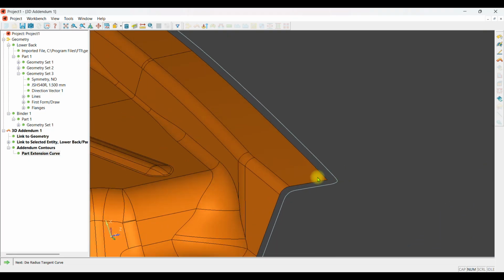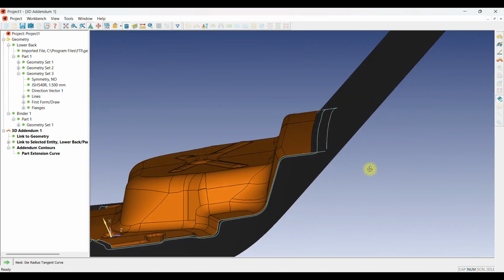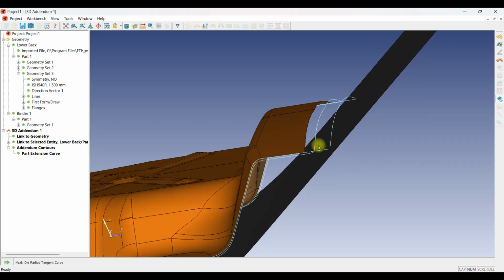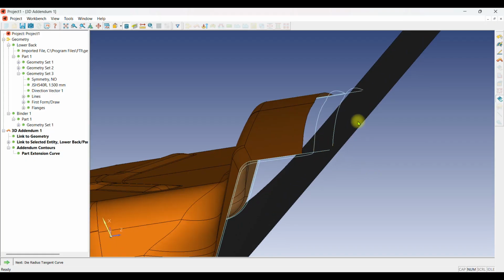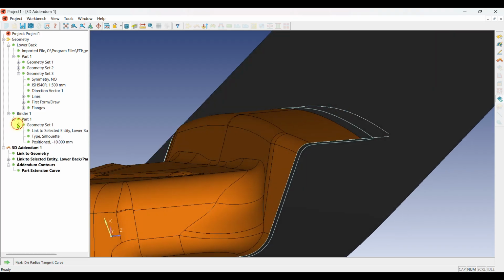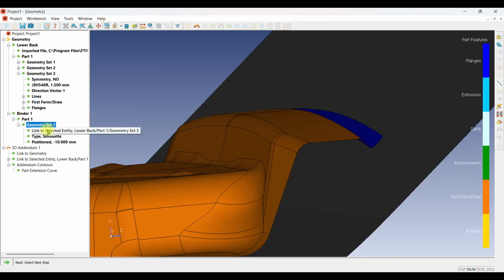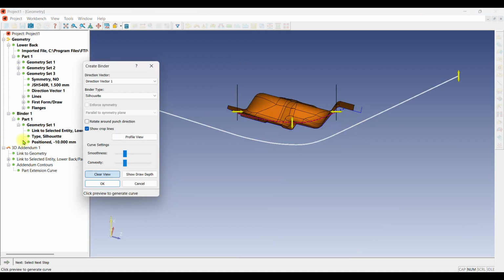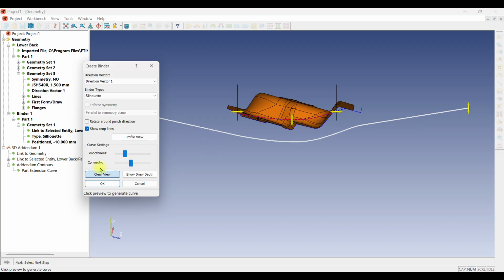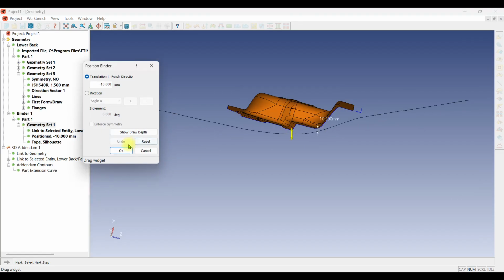And then I can click OK. Now in here I have something, the unfolded flange, so let me show. In here, show unfolded flange. Now please notice in here the unfolded flange surface is crossing the binder surface, so it means we must edit the binder curve in here. Like this one. You can go back, maybe change it a little bit like this. We change the convexity like this one. Okay, can click OK, so it will automatically be created.